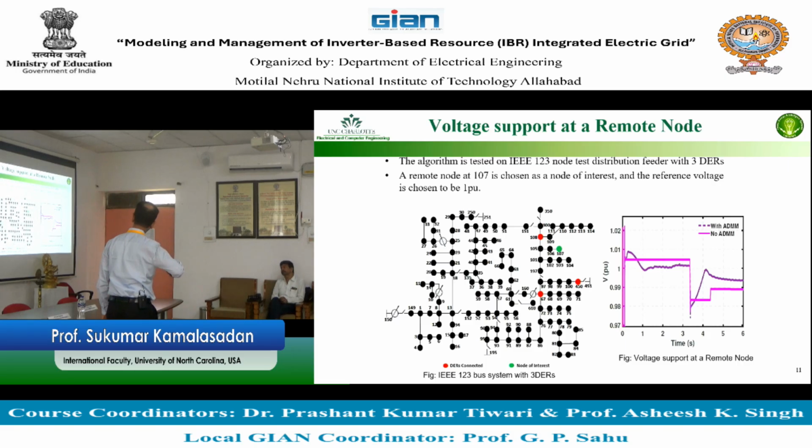The trick is these regulators are placed by the utility based on experience. Some of them are even rule of thumb, no math involved, just looking at the utility where the voltages are collapsing. So what is an indication? Those nodes are good indicators of where you put some devices, because they are the ones that are working. So we said, well, let's pick the worst one and put one small battery there and just control that battery. You were asking which one you should control, how many you control. It's very complex. So we call it a controllable asset. You only control that specific part. That is how you do it. I hope I answered your question.